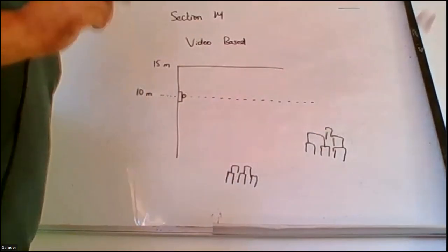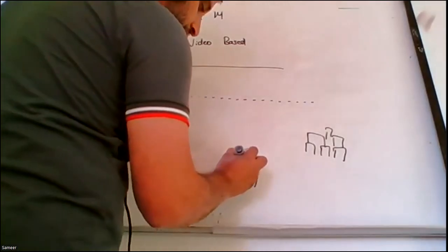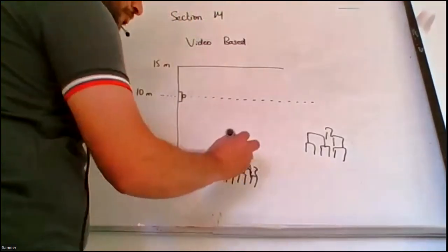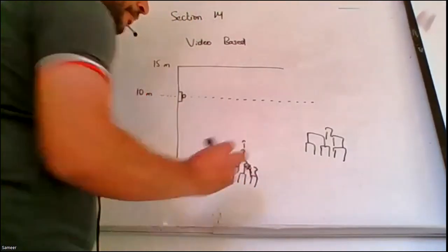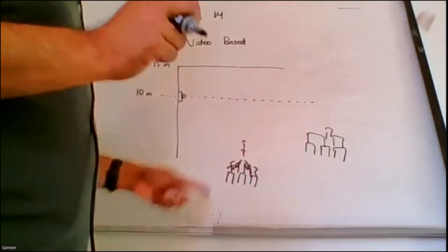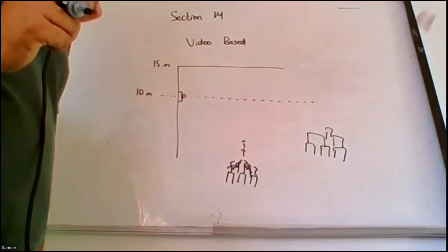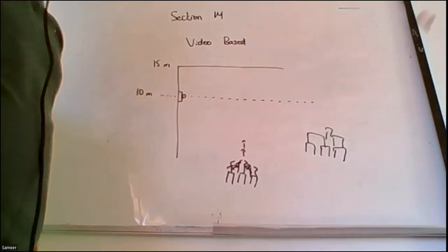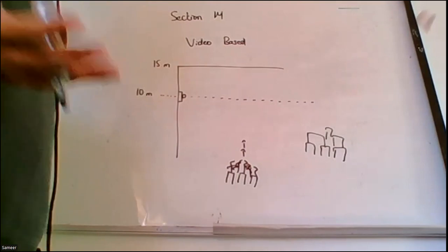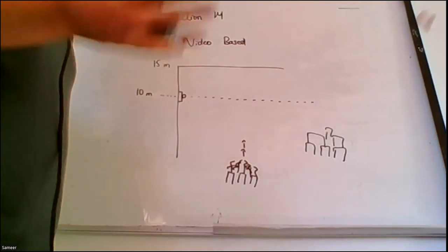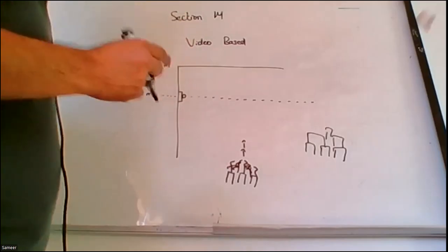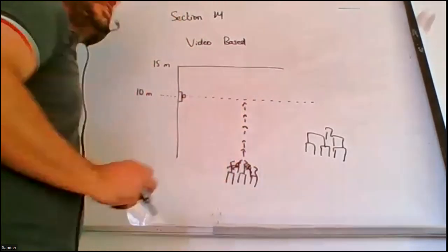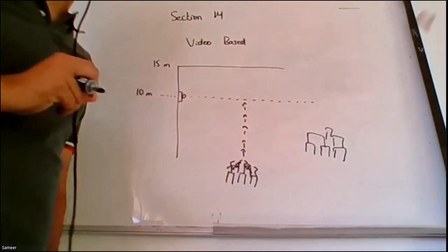So now what happens? Let's say the fire starts at a very initial stage. Flame starts. What will happen? Smoke will be generated. But to reach a height of 10 meters, the smoke is not enough. So what will happen? Unintentionally, we don't know, but the flame will become bigger and bigger, and eventually it will reach a point where it reaches the beam detector. Now the beam detector gets operated.